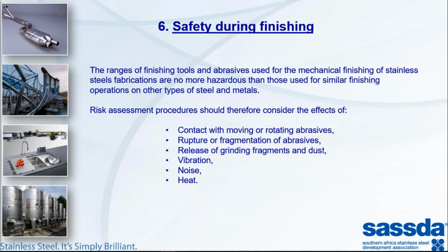Okay, safety also remains an issue, and I don't think I have to tell you any more about it, except to inform you that, remember, there are moving and rotating parts, and these parts are covered with abrasive material. These abrasives are also sometimes prone to fragment and fly all about the whole place. So safety glasses, that type of thing is important. And then once again, the dust and grinding fragments. Please clean your workshops and make sure that the dust is extracted. There's vibration, and you've got to be aware that especially the pneumatic tools are quite noisy, and these things create heat.